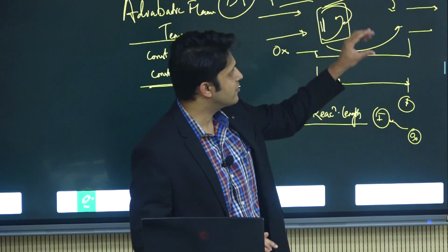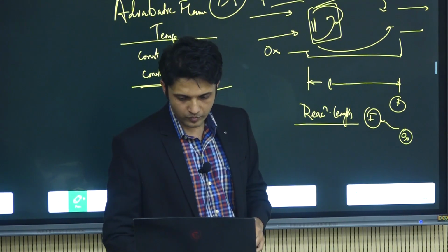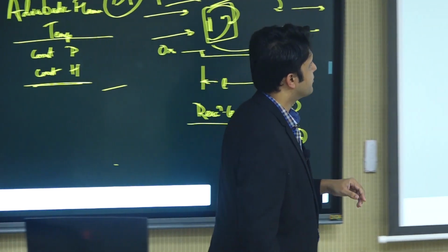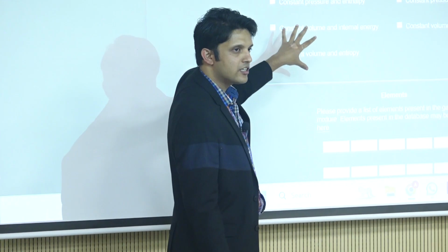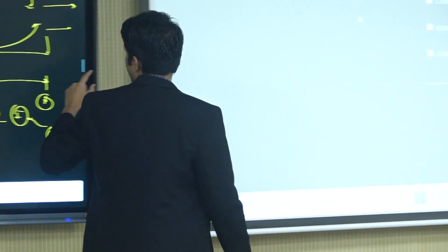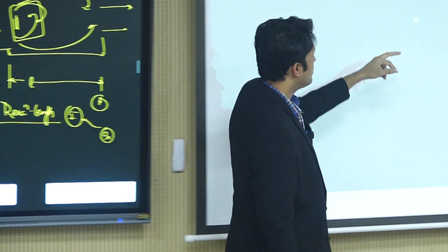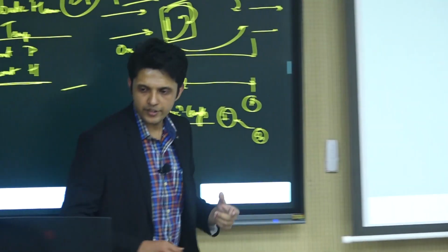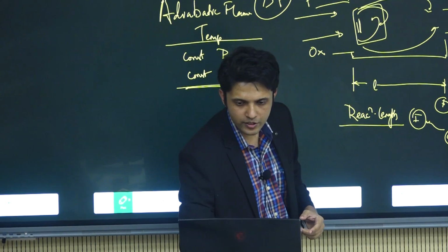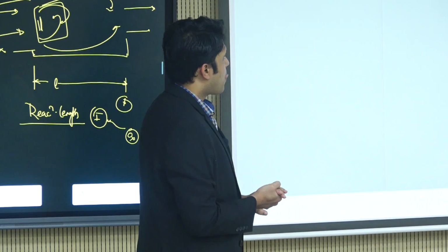So once we set these initial conditions and our guesses for the solver, we go to calculation constraints. In this case, you have these different kinds of processes given to you. For calculating adiabatic flame temperature, constant pressure, what should we select? We should select constant pressure and enthalpy, right? So if you click this, this is the one that we want to solve for.